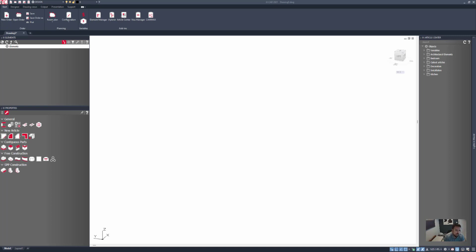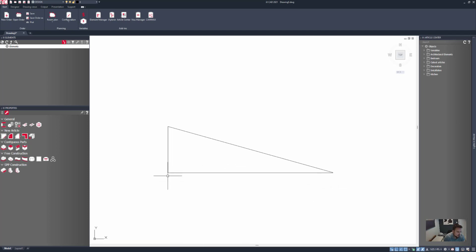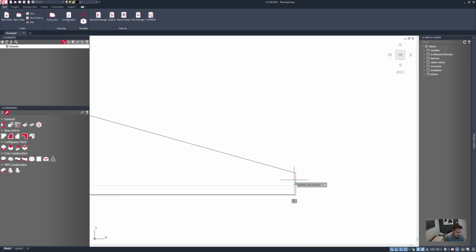So what I'm going to do is draw a polyline first of all using AutoCAD tools. I'm just going to go onto the top view and you can see I've got one in here that's already created. This was drawn with a polyline from this bottom corner here. Then I've traced round, and you can see that rather than giving me a complete point here, the line has actually come up, I think about 1 millimeter.